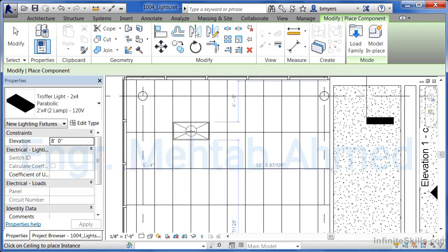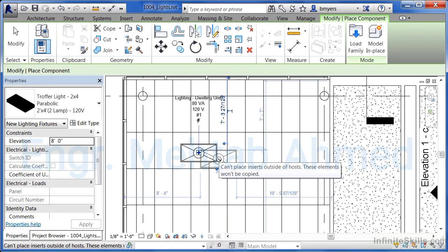One thing that you'll notice is that this light fixture is right on the center of where my cursor is at. Unfortunately, that makes it pretty much impossible for me to snap to any spot along the grid. So to place this, my own trick is to come in the general area where you want it to be. In this case, I'm going to put the light right inside of this square that I'm circling myself around. But since I can't click on an intersection to place it very easily, I'm just going to click once right here. And I'm going to hit escape a couple of times to get out of the insertion command.